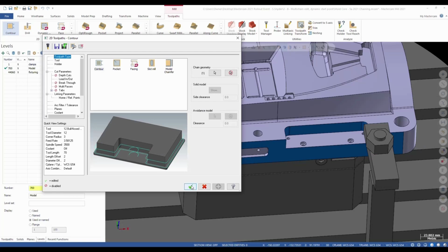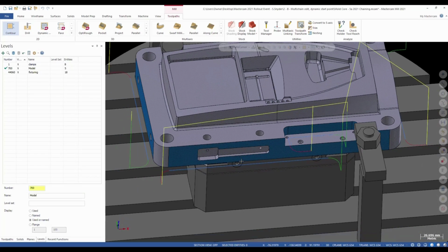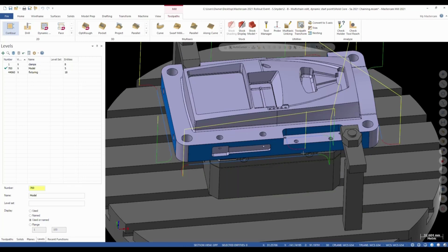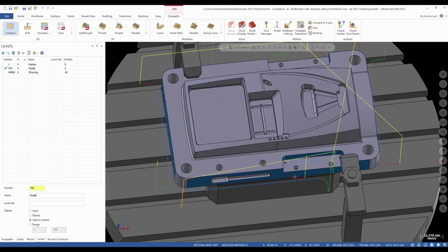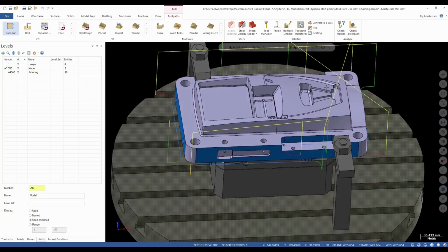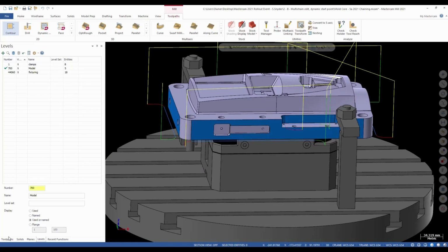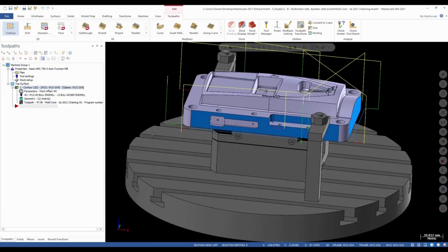And I'll go ahead and use the defaults that come into our contour path here just to see where our tool's at. And it looks good. Everything seems to avoid any clamps, and I got a nice entry and exit motion. I'll go ahead and say OK to this. I like it. Just put it in isometric view and fit. We'll make it look pretty and save it.